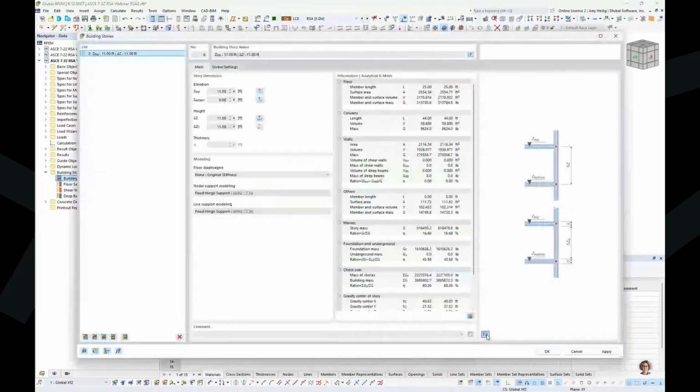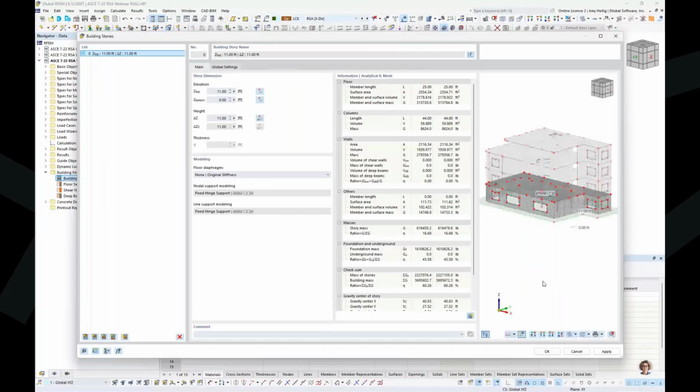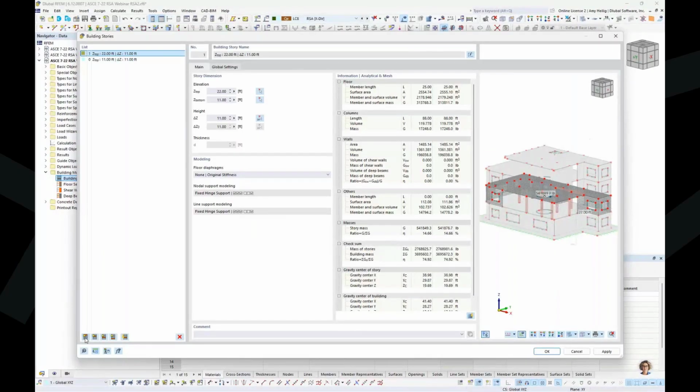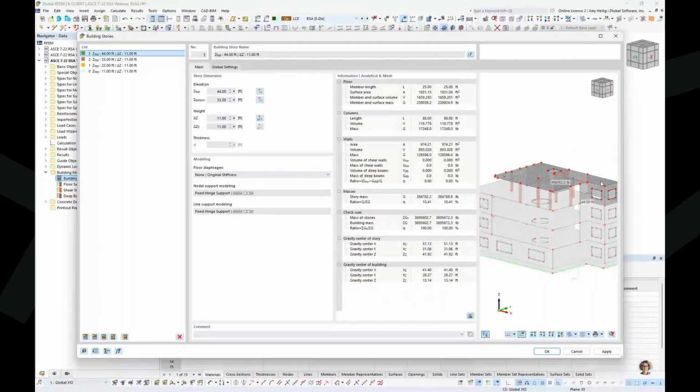So now in this general FEA program, we have the ability to define story levels. The program automatically creates our first story level at 11 feet. That's great. I'm going to go ahead and create the additional story levels at the additional locations here. Everything highlighted is essentially attached to this story level. The building model add-on also gives us the ability to define diaphragms like flexible, semi-rigid, or rigid. Again, not getting too much into the details today. We do have previous webinars that dive a little bit more into this, but the specific purpose right now is to define these specific story levels.